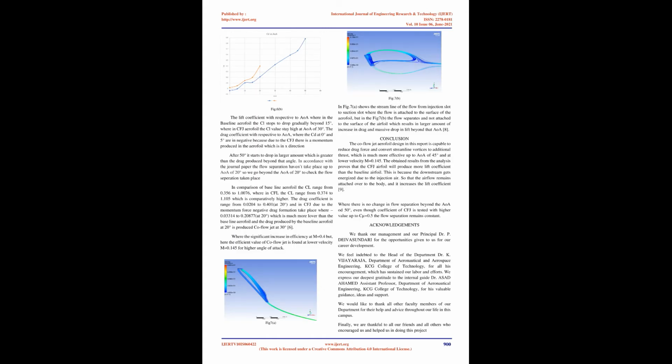After 50 degrees it starts to drop in larger amount, which is greater than the drag produced beyond that angle. In accordance with the journal paper, the flow separation hasn't taken place up to an AOA of 20 degrees, so we go beyond the AOA of 20 degrees to check whether flow separation takes place in comparison with the baseline aerofoil.